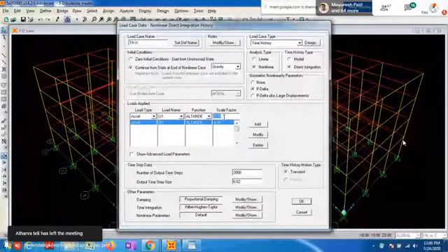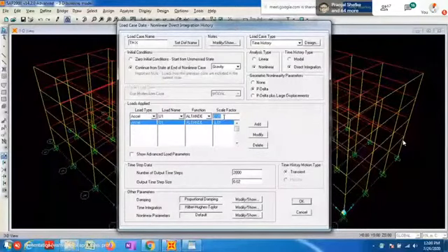Next, change to 0.2, multiply by 0.2, run the analysis; then 0.3, 0.4, 0.5, until your global drift reaches infinity. Then stop the incrementing. Then take the next ground motion. In this way, this is for the first ground motion. In this way it is to be performed.